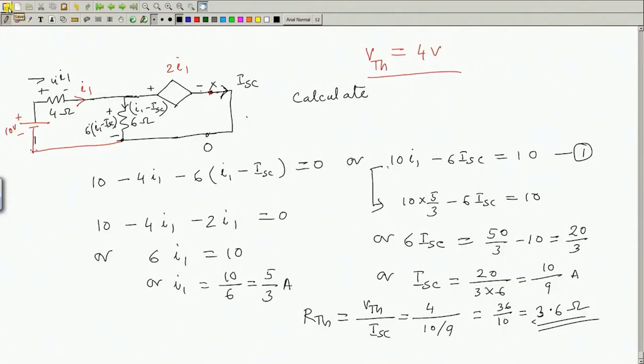Next time I will solve a problem, since the calculation of R Thevenin and V Thevenin is somewhat tricky. Although we replace the sources by their internal impedances, we do not do so with the dependent sources. Do not do anything, let them be in the circuit. Similarly, while applying superposition, or finding the short circuit current, dependent sources will be present always.